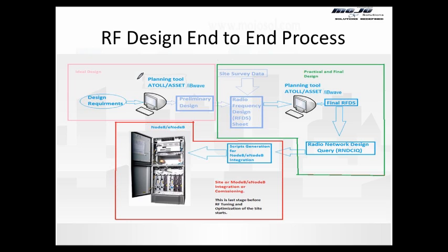that design, which was an ideal design, has to be implemented. Okay, when it has to be implemented, if the ideal design said the height of the site is 30 meters, but actually when you go to the site, it's on a rooftop, and you cannot install a tower, and it's 15 meters, then you have to adjust. You have to accept it or reject it or adapt to the site requirement. So you have to actually redesign the whole site and put it according to the site. Then you do a detailed survey and tell what is possible or what is not possible.